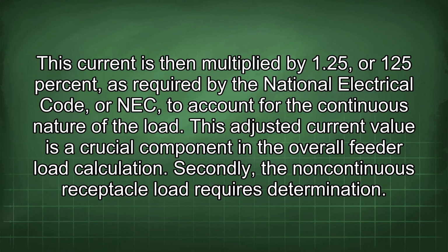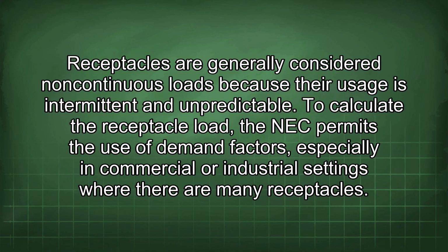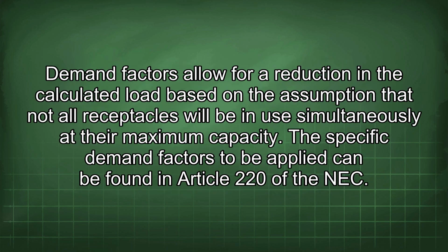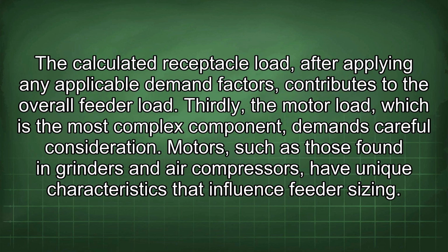Secondly, the non-continuous receptacle load requires determination. Receptacles are generally considered non-continuous loads because their usage is intermittent and unpredictable. To calculate the receptacle load, the NEC permits the use of demand factors, especially in commercial or industrial settings where there are many receptacles. Demand factors allow for a reduction in the calculated load based on the assumption that not all receptacles will be in use simultaneously at their maximum capacity. The specific demand factors to be applied can be found in Article 220 of the NEC. The calculated receptacle load, after applying any applicable demand factors, contributes to the overall feeder load.